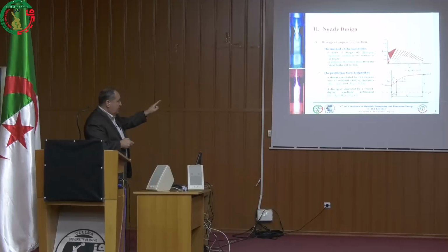The characteristic in this case is the Mach line, which comes from Ernst Mach. In his honor, we know the Mach number. These are the characteristics along which the properties are calculated. Properties like pressure, velocity, and we are here in two dimensions, so the velocity in x and y, the temperature, the pressure, the density, anything we can calculate.